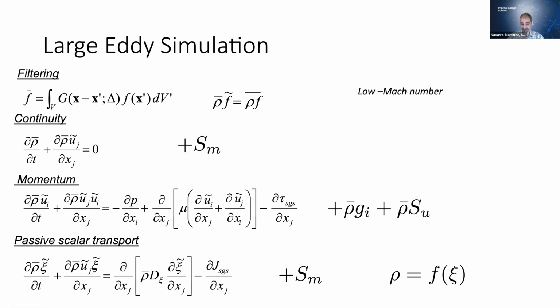We do have source terms of mass and momentum, and these are driven by the gun. The gun introduces mass and momentum. And of course, I forgot gravity. This is a buoyant flow. The gases are hot, so density is also a function of this psi indicator. Reactions outside the gun are neglected, so basically, the moment the gun injects the gases, this is all mixing.